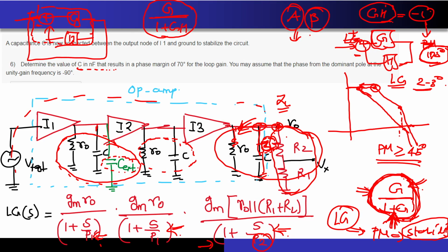If you do a phase margin analysis on this, what will this yield to you? What is this system? You have two negative feedbacks now, one negative internal feedback and one external feedback that you have intentionally put to check the stability of the system. Why? Because you are asking me to calculate the phase margin of the closed loop system. So if it comes out to be, let's say, 30 or 40 degree, then I can ensure that if I put this transfer function in the negative feedback, then this system will become stable. But am I checking the stability of this system or of this system?